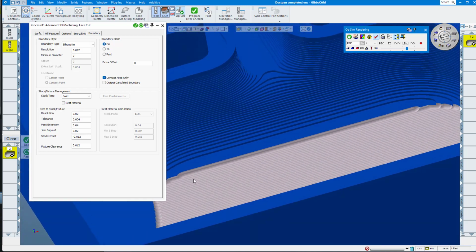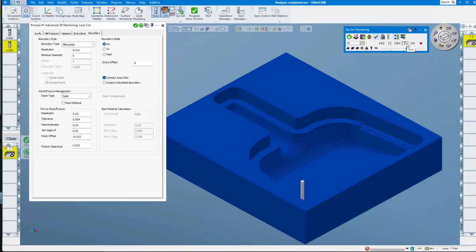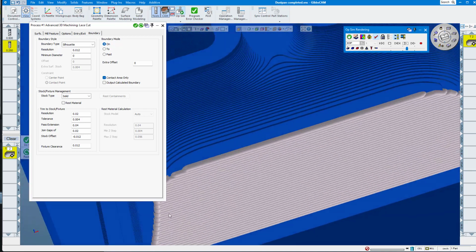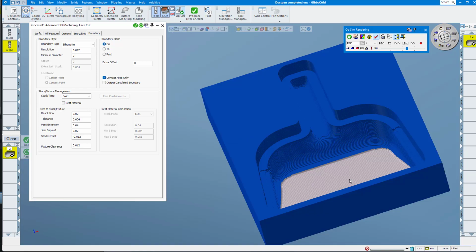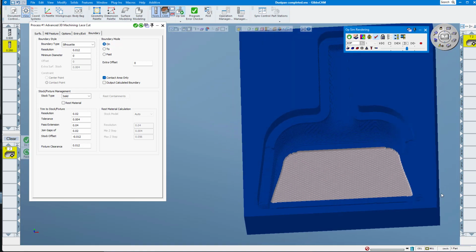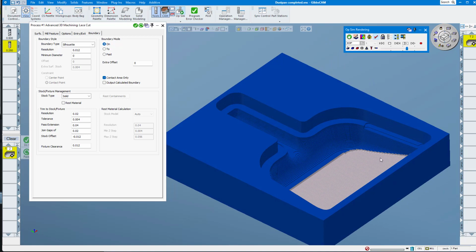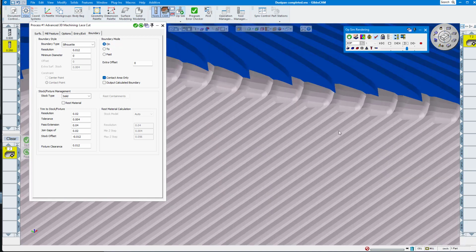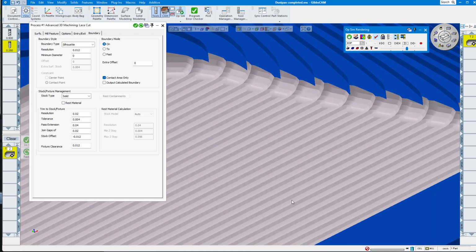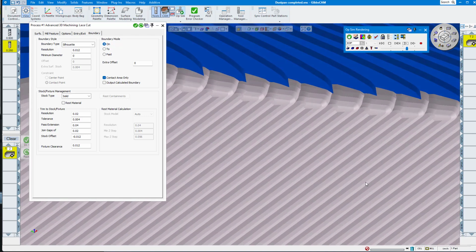Again, our lace toolpath. So there it is, huge step over. But the reason I do this too is I really want to show you scallops. So I think we may not all know what scallops are. We probably all know what they are. But just for those that may not, if we look at this, you can see there are these little pyramids. Everybody has a little different name for them, but we have these little lines, and that's the radii that meet in between that ball cutter coming in, and that's what gives you a bad or good surface finish. So you really want to decrease the amount of extra material when you're doing 3D machining